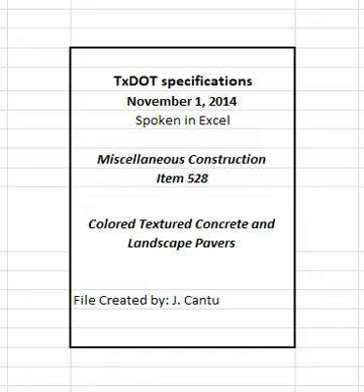Place paving units on an uncompacted, screeded sand bed to the required laying pattern shown on the plans. Align all joints and provide nominal 1/8 inch gaps between adjacent units. Place the first row to a butt edge restraint with a gap of 1/8 inch. Place at a suitable angle to the edge restraint to achieve the required visual orientation of paving units in the completed pavement. Lay full-size units in each row first, followed by closure units consisting of at least 25% of a full unit. Cut units using a power saw.